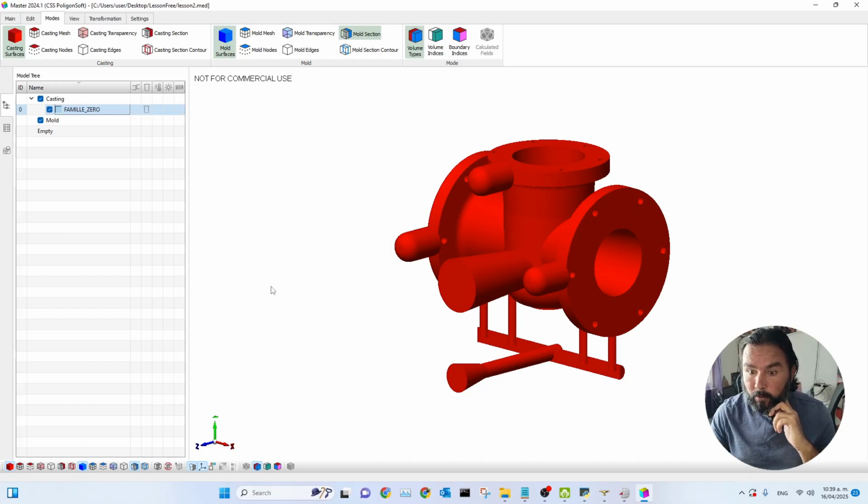As we can see, the model opened in a position that seems incorrect. Why did this happen? Because, as I mentioned earlier, the gravitational force in the PoligonSoft program is directed along the y-coordinate. And if we created our model in a different coordinate system, when we open the model in the program, we will always see these kinds of things. How to correct this error?